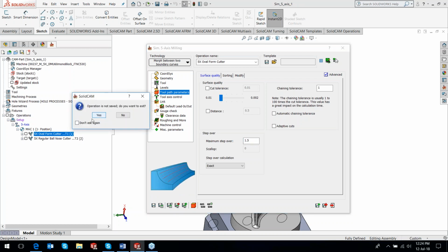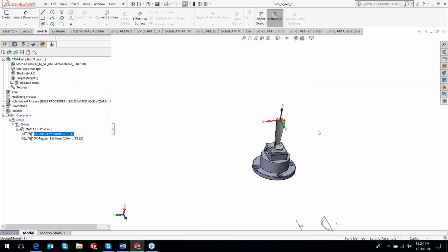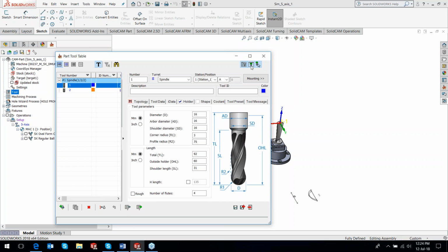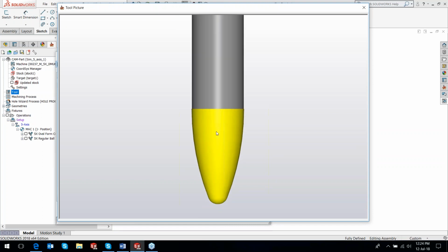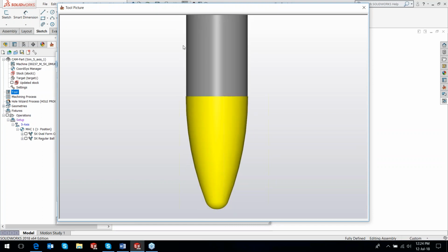Now, there have been questions asked to me on what should be the tilt angle. It's obvious that if I have this tool here, and let's assume that I'm just cutting a straight surface. I'm cutting a straight surface. So if I keep my tilt angle 90, I will have this portion of the tool in contact, the upper portion, the place where the cutting edge ends. That's going to be in contact. I don't need that. So what should be my tilt angle?